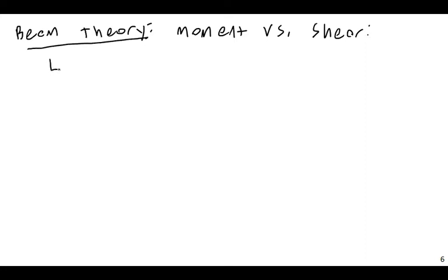When we look at a W section, if you recall from mechanics of materials and from our earlier discussions, you'll remember the logic behind why a W section is shaped the way it is. Let's review. Why is a W section built like this? Why do we have a lot of the area far from the centroid? What is the purpose of that? To resist more moment. Yes, exactly.